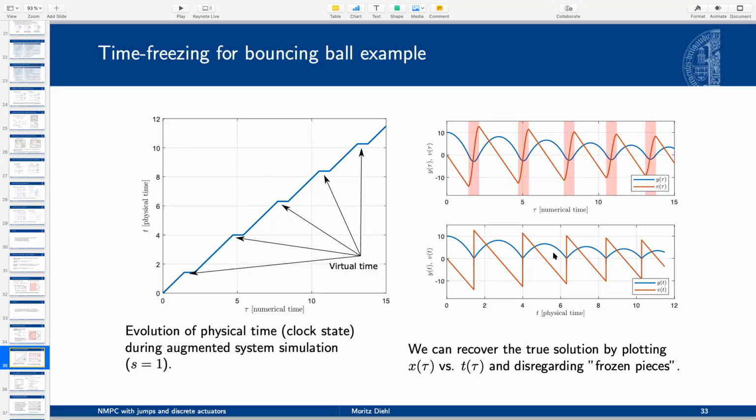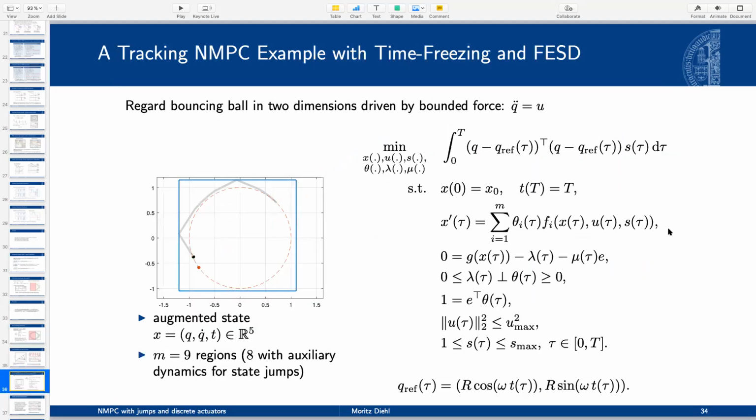Depending on how you formulate your optimal control problem, you need to ensure that obviously these hidden dynamics are not in your objective. But anyway, they would be weighted with 0 because the time is frozen, and so there's no integral objective summed up. So basically, these hidden dynamics you just forget about, not only in the plot, but also in the optimization problem. They don't appear. And now you can use that to do things that you couldn't do before.